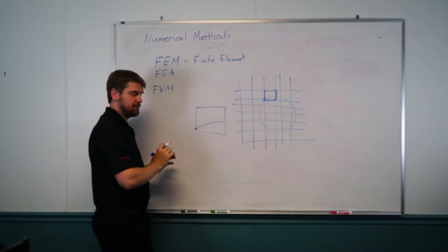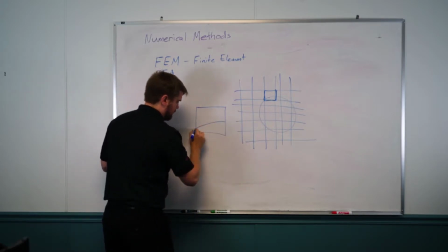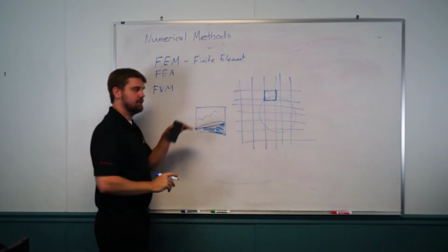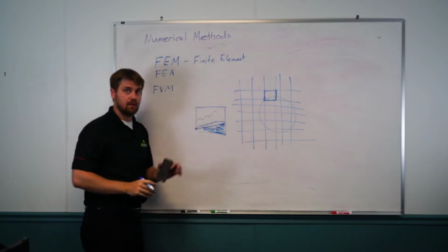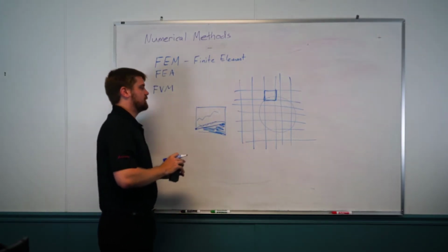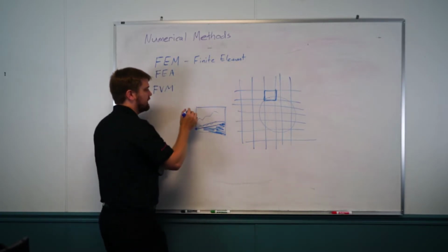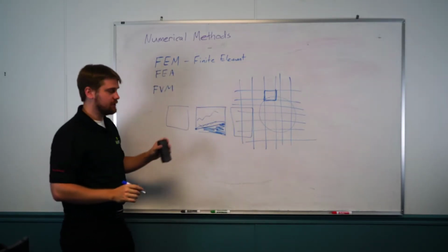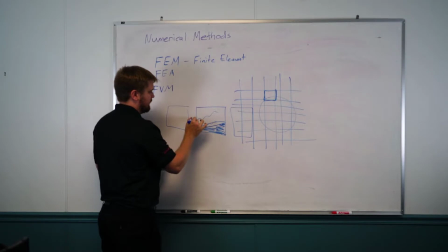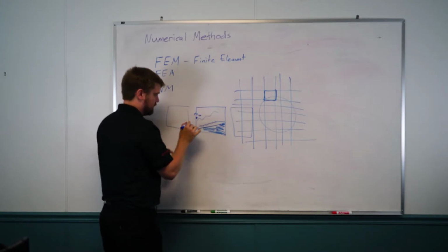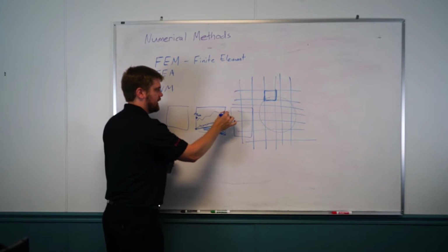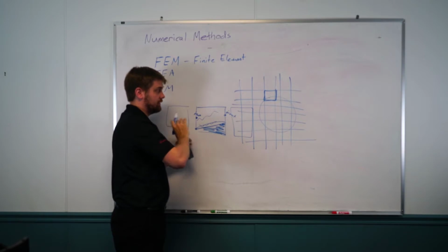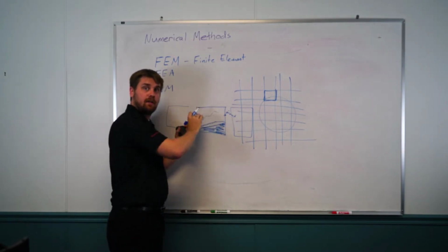But an element is a simple thing, a cell is a simple thing. It's not going to notice the curvature here. It's going to say there's a solid region here, and this is a fluid region here, including this region is also part of that fluid region. And it solves fluid dynamics equations by linking the cells together, the cell immediately adjacent to it, and adjacent to the other side. They have their own equations. And the idea is that the mass flow rate coming in has to be equal to the mass flow rate leaving. And so you see a bigger area coming in, a smaller area going out. That means the velocity has to be faster over here. Gives it a nozzling effect.